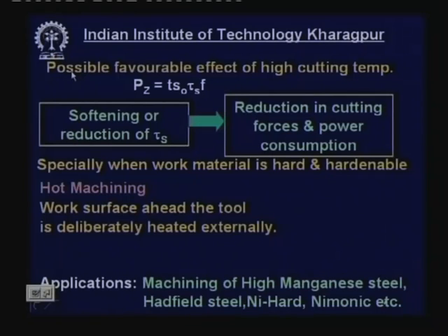Is there any favorable effect on this? Very rare. Favorable effect of high cutting temperature is very rare. Anyway, the possible favorable effect may be, here you see that we know the cutting force, main cutting force PZ, depends upon the depth of cut, feed, the shear strength of the work material under the cutting condition, and form factor.